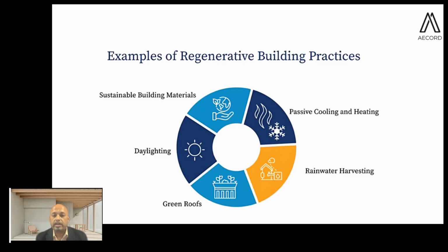So in arid climates, you may go for passive cooling, and in cold climates, you may go for passive heating. How much time in a year you can really depend on passive cooling and passive heating can dictate your energy consumption of the building being 40 to 60% lesser than your conventional air conditioned building. When I say air conditioned, it can be heating or cooling. So when you replace your air conditioning with passive methods of natural ventilation, of cooling, or trapping the heat inside, and gaining heat from the sun and trapping it into the building, hence reducing the heating energy, you can save anywhere up to 40 to 60% of your annual air conditioning load. When I say air conditioning, it's both.